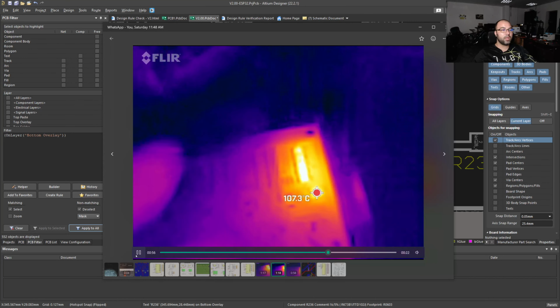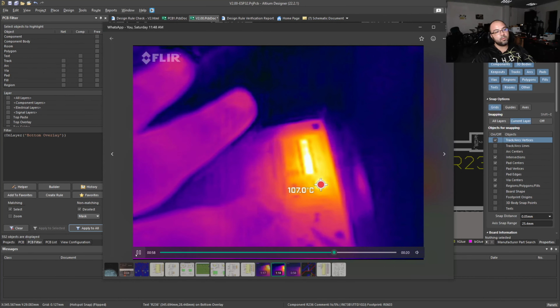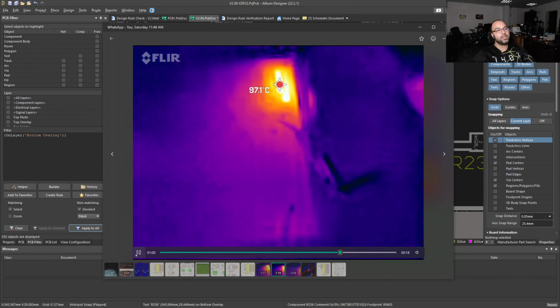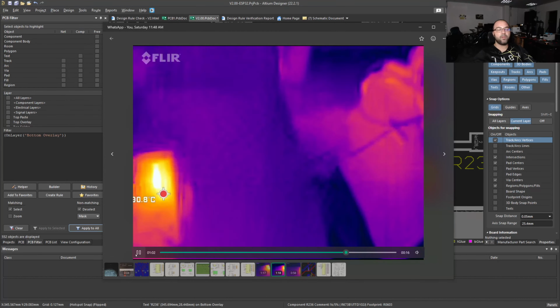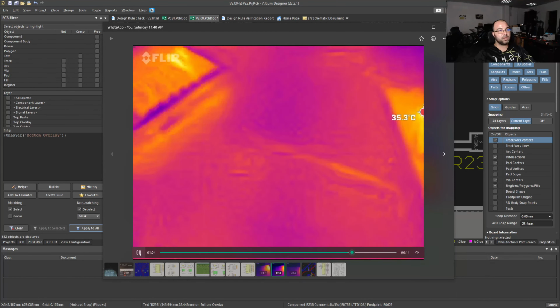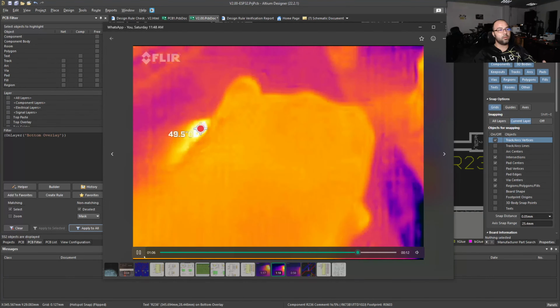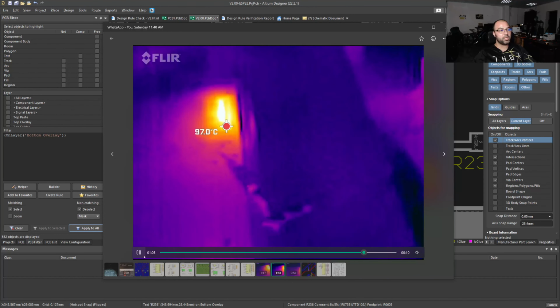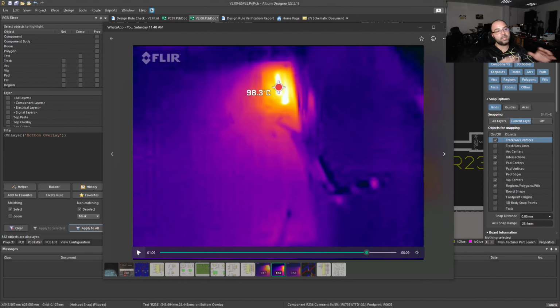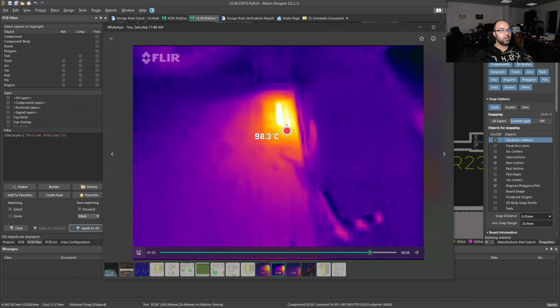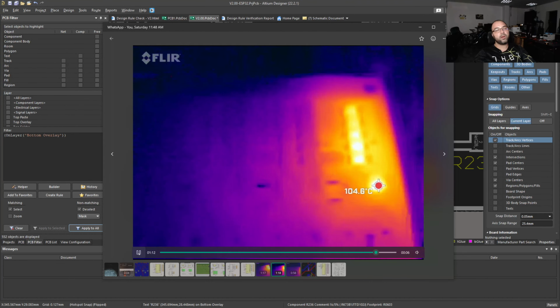I'll do multiple tests after I get the final PCB, and in case I have to update the fans, I will upgrade the fans for the rated current that we're going to place on that charger. We might sell a version that's rated to 2 amps, and we might have another version that's rated up to 4 amps with improved fans for better airflow.